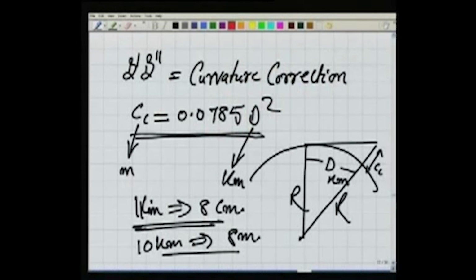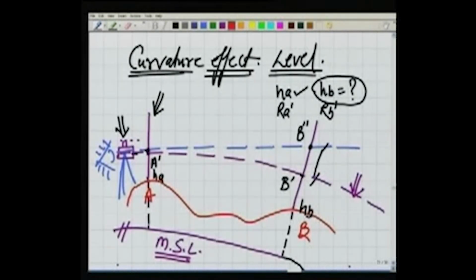Now in our case here, the line of sight, or the graduation which is actually reaching us, is also being affected by refraction of the atmosphere, because the line of sight will not now be horizontal, rather it will have again a little curvature.